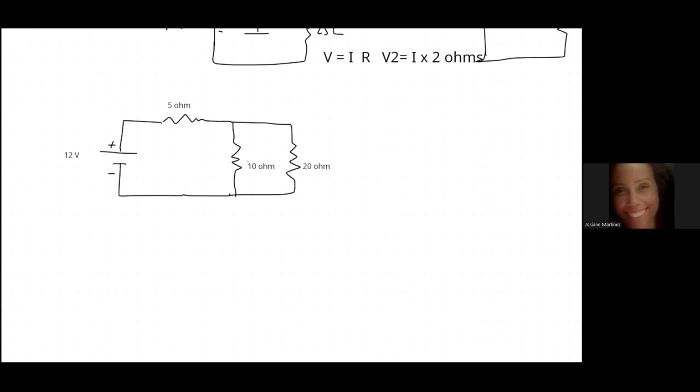We're going to simplify the 2 parallel resistors first, because they're the ones that we can obviously see are in parallel. Their 2 top ends are tied together, and the 2 bottom ends are tied together. There is no element between them, okay, where the current enters and exits are tied together.